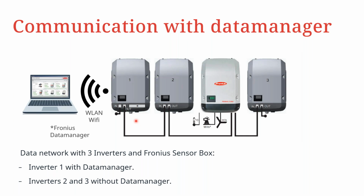In the case where you have multiple components, that is multiple inverters, please ensure that only one data manager is turned on. If there are multiple data managers in the system, please ensure that only one is functional. This can be done by simply turning off the other data managers in the other inverters.